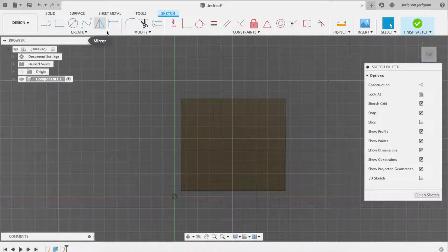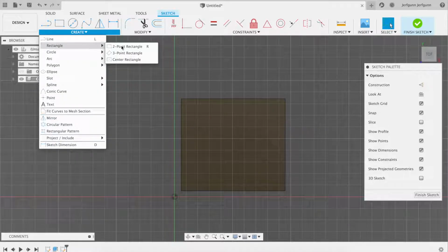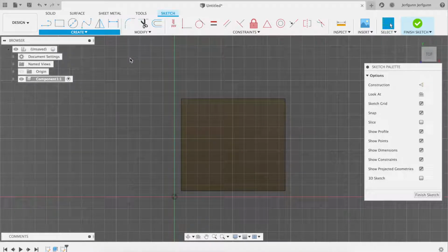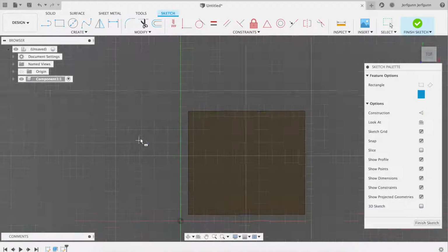Now, if you've got a rectangular pattern of 4 bolts, an easy way to do that is to use a rectangle. So you draw a rectangle, and then you locate the circles that will become the bolt holes at the corners, right? So it allows you to quickly draw a pattern of circles representing the bolt pattern. So we'll go to Sketch, Rectangle. I'm going to use a center rectangle for reasons that may become obvious a little bit later.